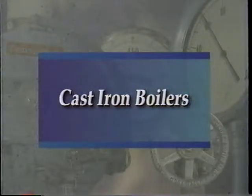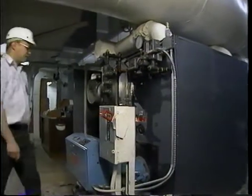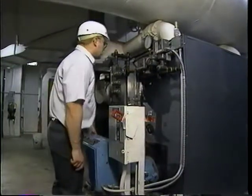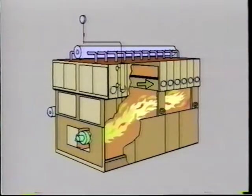Cast iron boilers. Cast iron boilers operate similarly to water tube boilers, but they do not have water tubes. The flame and gases of combustion are directed through cast iron sections of the boiler. The cast iron sections, similar to tubes, act as vessels which contain water. The water is heated in the sections and converted to steam.